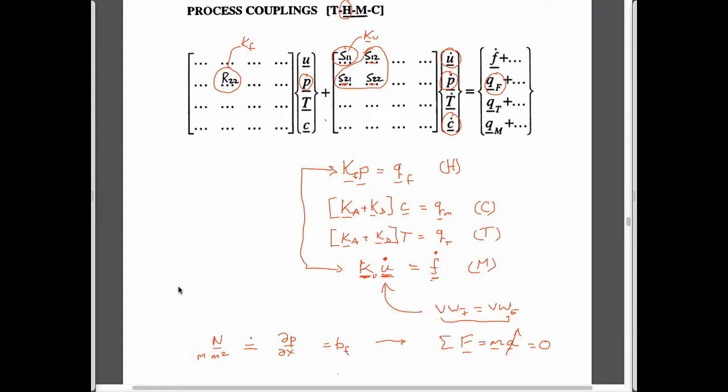And so really all it's saying is that if you have pressure that's acting on a block, and it goes from some magnitude upstream to some smaller magnitude downstream as it acts on this block, then if you look at equilibrium, the pressure on this side is 0, the pressure on this side is finite, and it's changed that pressure over some length. And so this mismatch in pressure as you go from one side to the other is a force that has to be accommodated in the system somehow. And so that's the component that we'll see goes into the force equilibrium equations which define this.